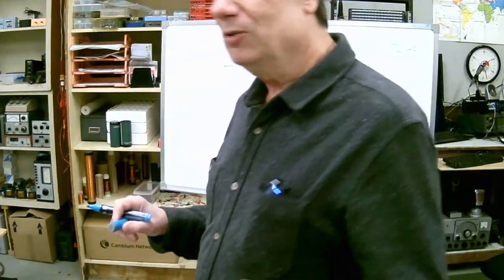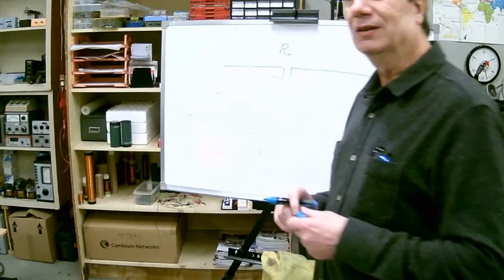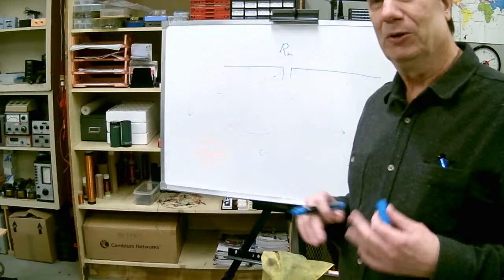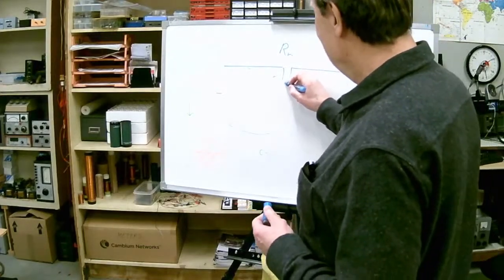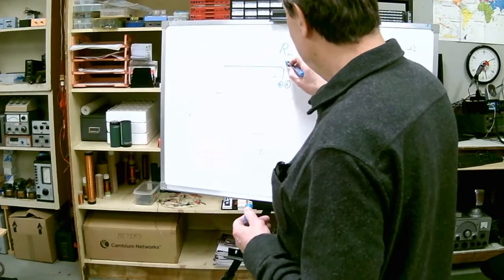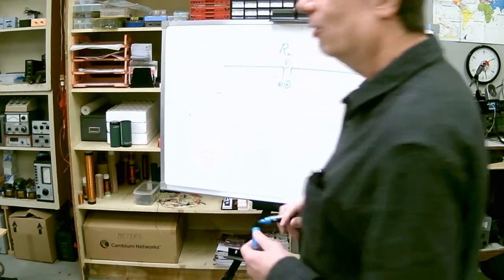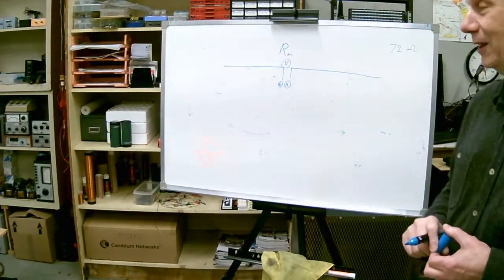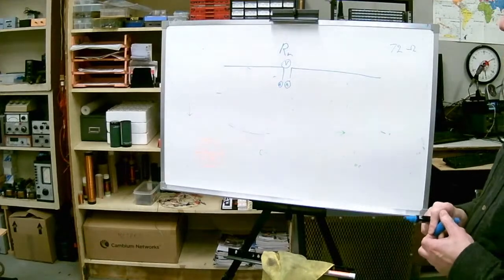But what we do is radiate into space. So this radiation resistance can be calculated just as if it's a real resistance. We can measure the current and the voltage and multiply them together here, and lo and behold, it's going to be real power. And we're going to actually radiate that power. That's the actual power that does work for us by radiating a signal into space, which is the whole idea of an antenna in the first place, right? Yes.